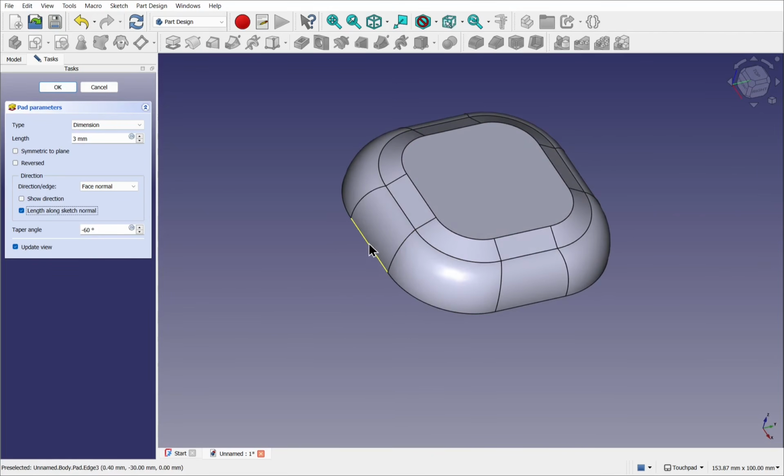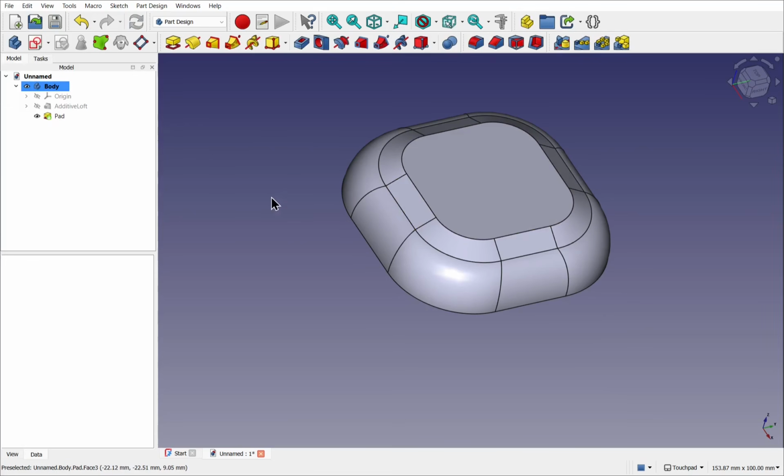Because we've created a straight line here, as it curves up here, this won't be a planar face, but this one will be because we just created a pad from here and tapered this inwards. This means this face can be easily connected to without using the advanced attachment modes. We'll be using these faces later. Let's hit OK. Now it's time to create the finger well.